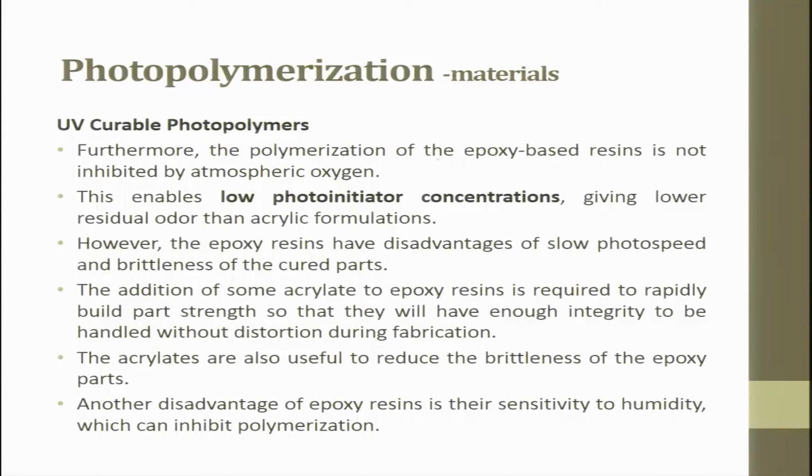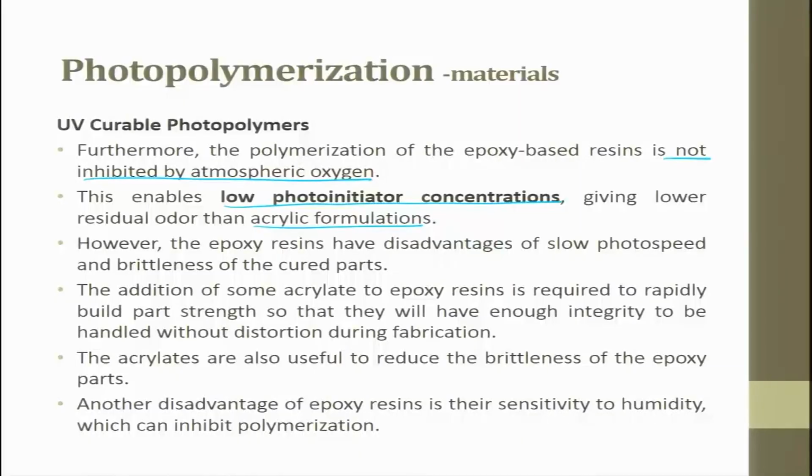Furthermore, the polymerization of the epoxy based resin is not inhibited by atmospheric oxygen. This enables low photoinitiator concentrations, giving lower residual odor than acrylic formulations. Okay. So, this is not inhibited by atmospheric oxygen. Epoxy does not react with atmospheric oxygen. This enabled low photoinitiator concentrations, giving lower residual odor than acrylic formulations.